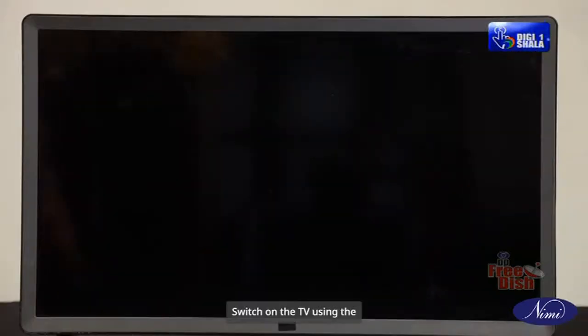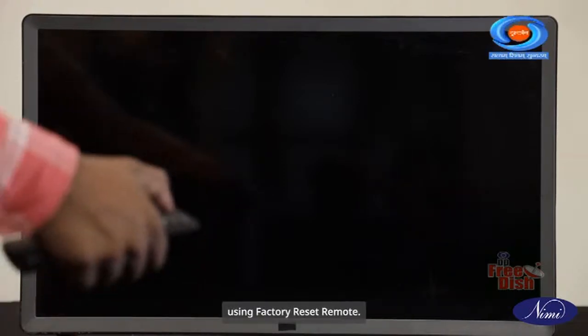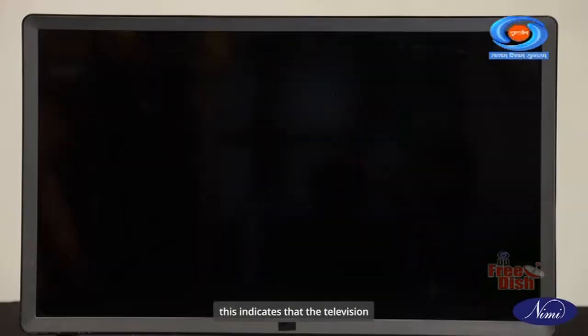Switch on the TV using the remote controller. Then check the different patterns using the factory reset remote. Observe the front panel of the TV for the LED indicator. If it does not illuminate, this indicates that the television is not receiving power.